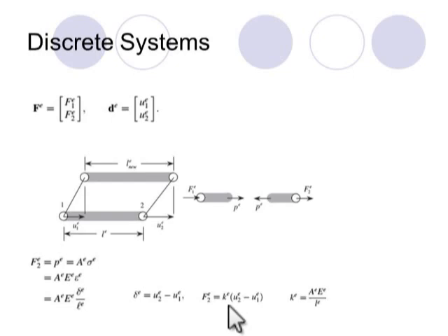And therefore here we call the small k the stiffness. It is similar to the stiffness of a spring, which means that a truss element acts like a spring. And if we put all the expressions into their places, we can see the value of k, the stiffness of the truss element. Basically, k is equal to area multiplied by the Young modulus divided by the initial length.